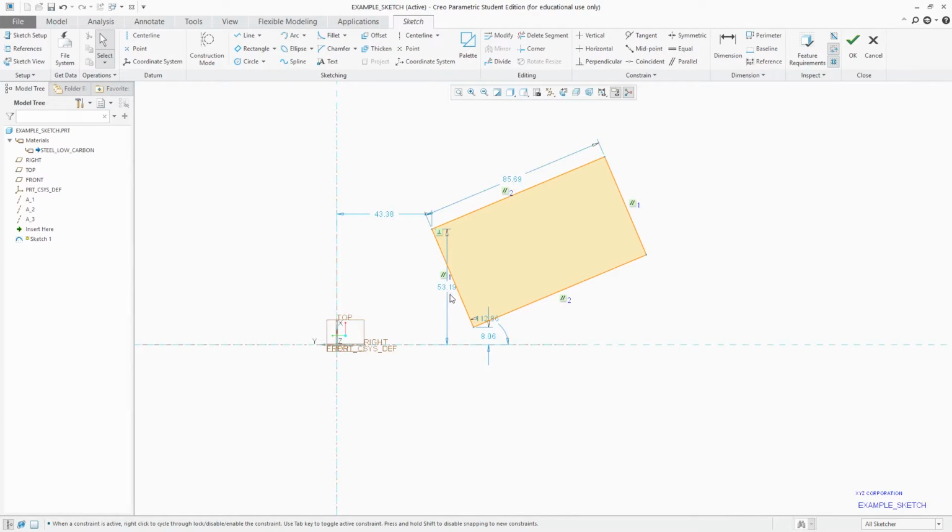I need to give it a value. Let's say for example you want to give a width value, not this one. So what you can do, simply select any line, and here you can see length. This mini menu will appear automatically whenever you click, like this here.